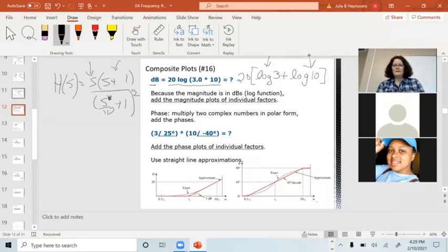So that's the factors on the top, in the numerator? Yeah, there are factors in both the numerator and the denominator. The ones in the denominator are just going to be negative, because poles fall. That's why poles are negative. So you combine the plots of the zeros in the numerator as well as the poles in the denominator and just add them together into a single plot? Yes. I find the Bode plot of each one of the factors and I add them together.